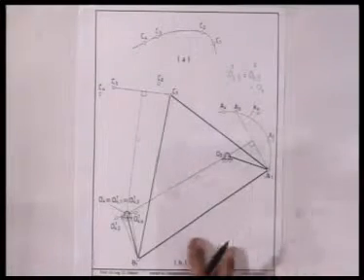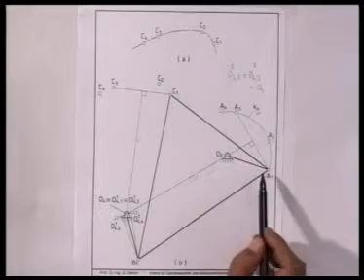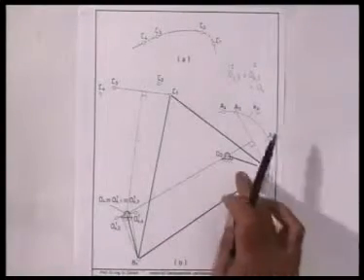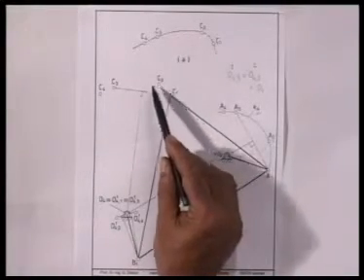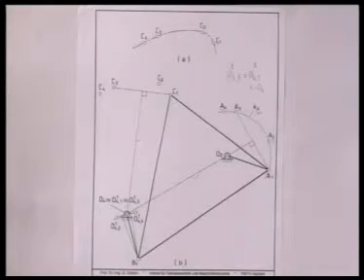So now I get the 4R linkage function path generator O2, A1, B1, O4 with C1 as the coupler point. Once this linkage is moved, this point C will go from C1, C2, C3 and C4. So we have got a 4 position synthesis path generation problem solved by using point position reduction technique.